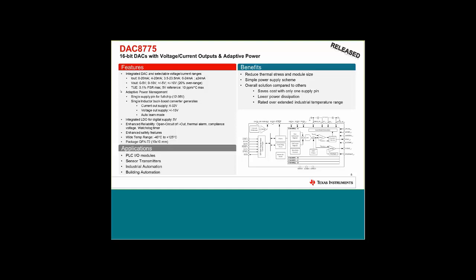But if we're talking about something with the DC-DC active, and again, in the case of plus minus 24 milliamps, it's closer to 2 milliseconds to slew from negative full scale to positive full scale. Full tracking doesn't apply for the voltage output, so it would always be 1 microsecond.